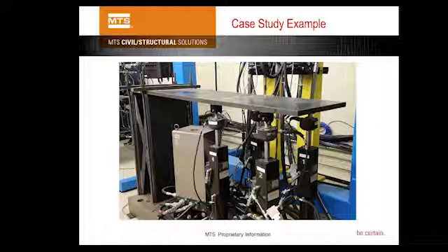It's like a steel plate you can see here on top. This is your testing article. It's like a cantilever steel plate. And then there are 4 vertical actuators supporting this plate. The idea here is to simulate an aircraft wing, right? Then you can do a lot of proof of concept and algorithm validation on this. So that's the test rig we use.